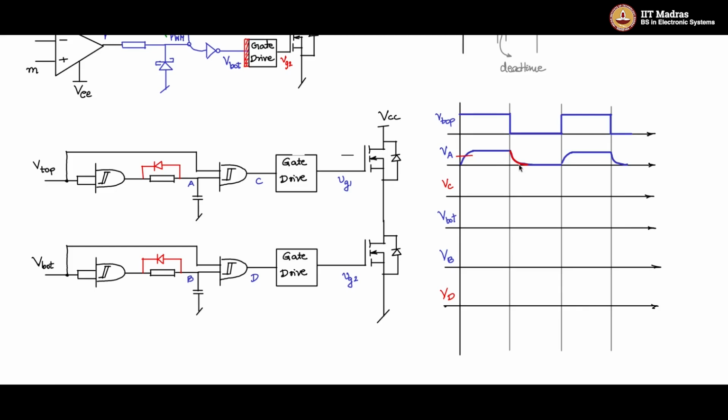this falling. Actually, you don't need to be worried about this falling, because as you see from the waveform, this will be dominating for this. But you need to discharge this C as quickly as possible so that it is back in action for the next cycle. If the duty cycle is small or large, you need to have the capacitor back in action as quickly as possible. So that will decide the minimum duty cycle.